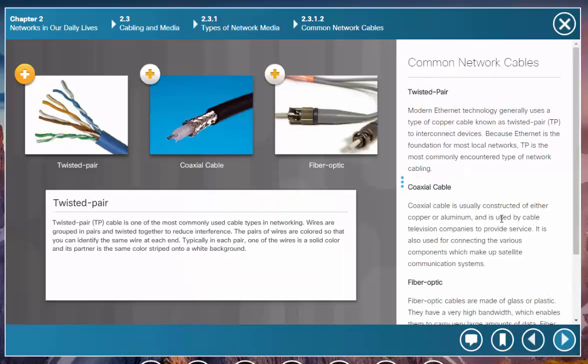So the most common type is copper cabling. And we have twisted pair cabling, which is a set of 4 pairs, 8 wires, for data cabling anyway. Each one you'll notice has a slightly different twist rate. This is to reduce what is called crosstalk or interference between wire pairs. You've got some interference regardless. You also know that UTP is not extremely resistant to EMI or electromagnetic interference.